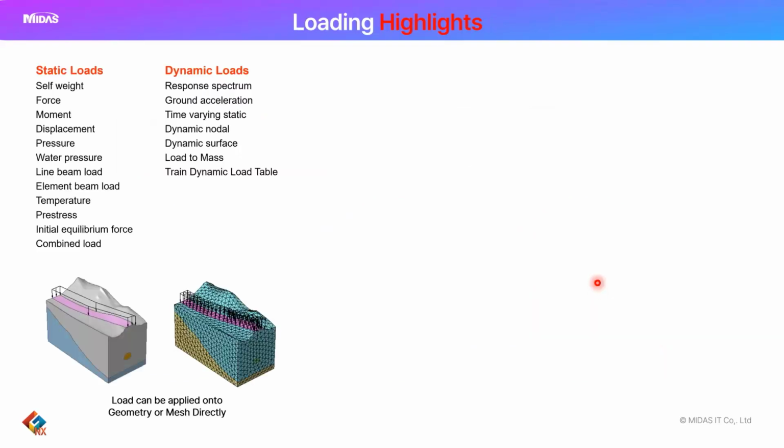And in terms of loadings, you can apply the loads either on the geometry or on the mesh. That's an important part. And all the different kinds of loads, like beam loads, concentrated loads, concentrated moments, and displacement loads. And even the load combinations can also be provided in this software. In addition, you can provide the dynamic loads as well.